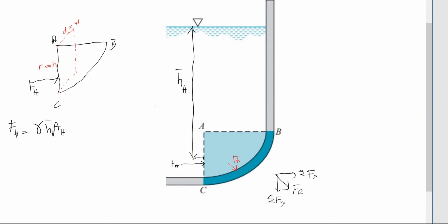Okay, and that is second. Draw the free body diagram. There's another force here. Since there's water above this curve, it's not open to the atmosphere. There's water above, so there will be another force acting at the top, somewhere here. Since there is no change in the elevation, it is acting at the centroid because pressure is distributed equally. So at the centroid.